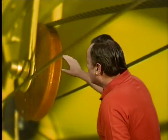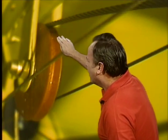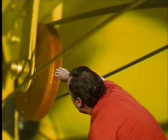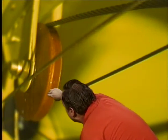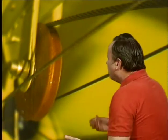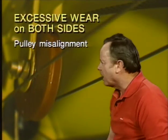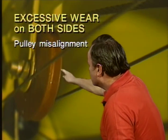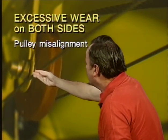Now, let's assume you're out in the field as a working mechanic and you are inspecting a control cable pulley like this one right here, and you check the pulley groove and you see excessive wear on both sides of the groove. Now, you look in here and you see a lot of wear inside that groove on both sides. What would that tell you? And the answer is it would tell you that you have pulley misalignment. It's not lined up properly. So excessive wear on both sides of the groove of a control cable pulley would tell you that you have